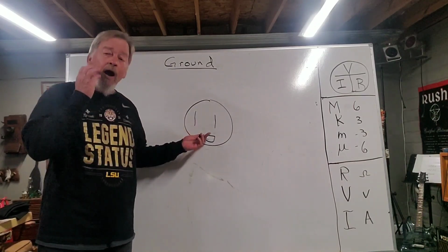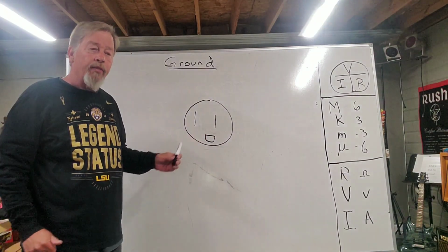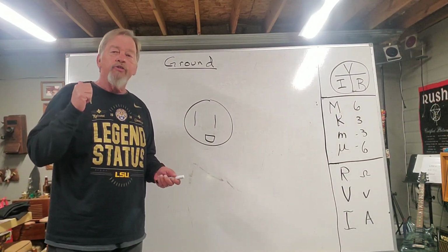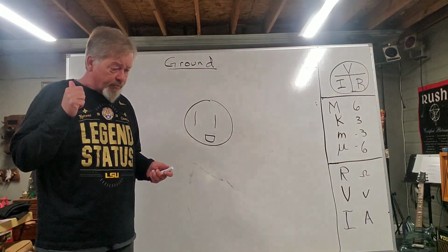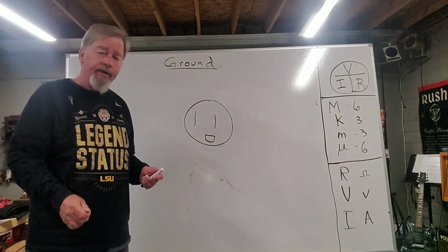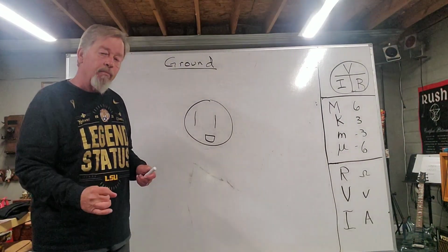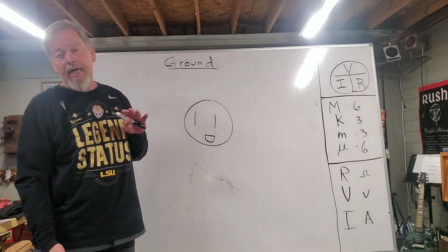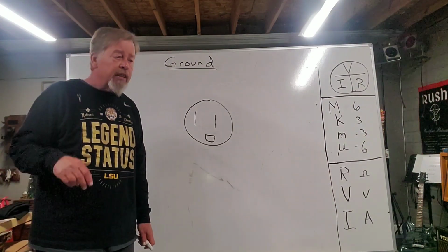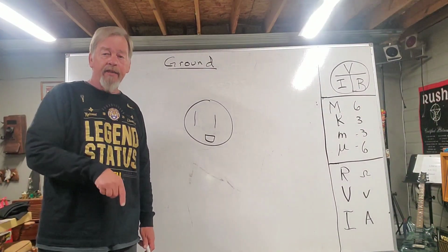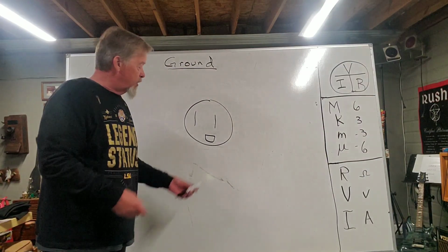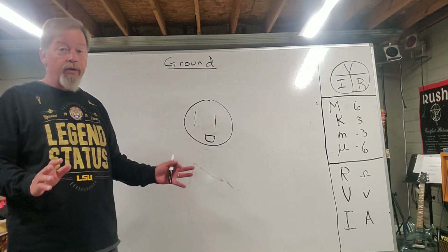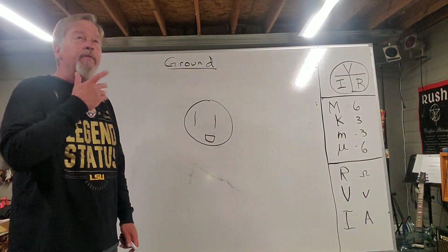Now this ground is actually connected to a wire that goes out by your meter pan. And if you go look at your meter pan, you'll see a bare copper wire coming down and attaching to a little metal post. Well, that metal post is down in the ground, probably about 6 feet. And so that connection puts ground potential at this point on the receptacles. Now, what good is that?